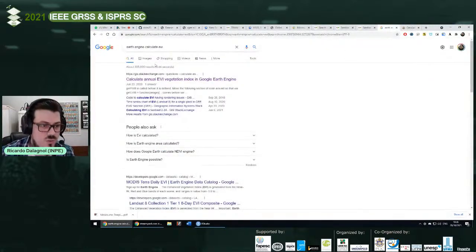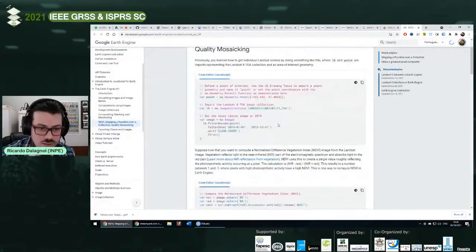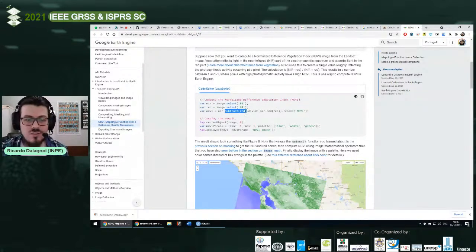There's another different way, more simple. Let me try NDVI because I looked at this yesterday. There is a quite simple way to calculate this. This line shows how you do this math with the different bands of the imagery. For example, you can take one band, subtract another band, divide by one band plus the other band. So this is NDVI, a normalized difference index. If you want to calculate EVI, just look for the formula and you can type in one band plus another times another. You can just use this kind of syntax to do that. I think it's a bit simpler than that previous example.